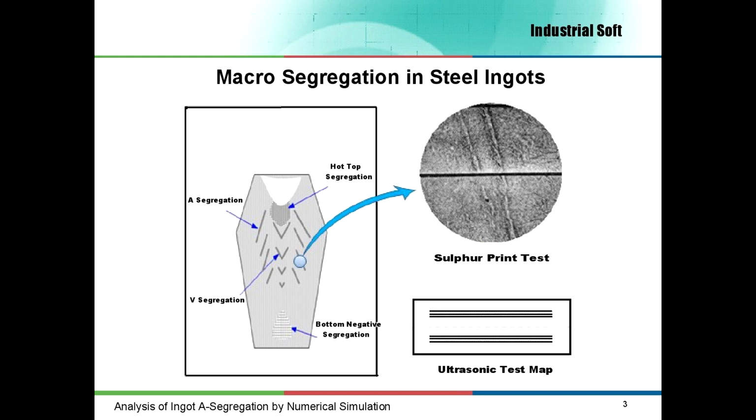Instead, as observed in real products, because of the material heterogeneity we can have problems meeting the specifications concerning mechanical properties. So, if we want to avoid this kind of problem, we have to control the segregation process, and one of the ways is to choose the right ingot size as a function of the chemical composition of the steel.